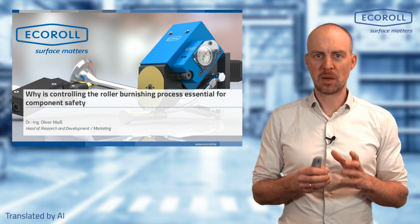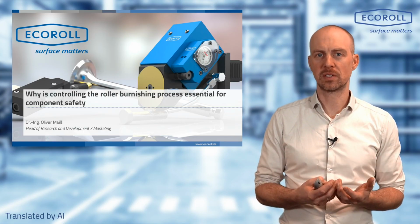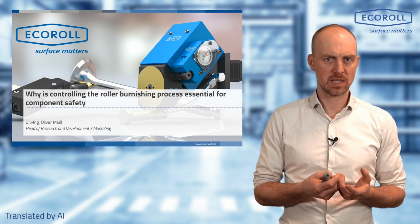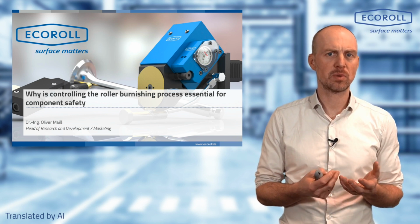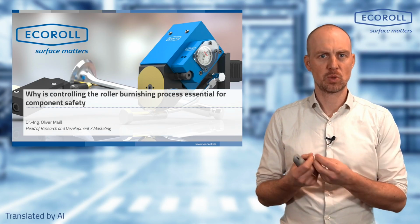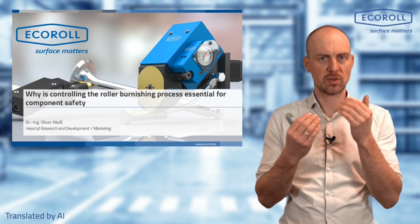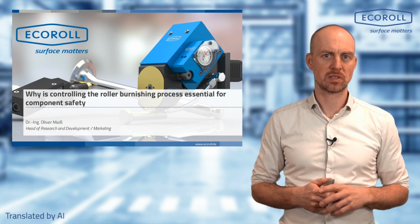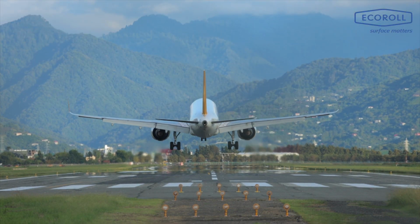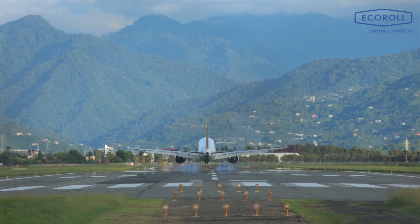And it's basically about significantly improving the deep rolling process by wanting to control it. And not just controlling the rolling force as a parameter, that seems relatively simple and obvious. No, we wanted to control the surface pressure between the tool and the component in order to significantly reduce the difference in residual stress between different components. This is crucial when I have components that are designed to be particularly safety relevant, and we really can't afford to make any mistakes in the process design.